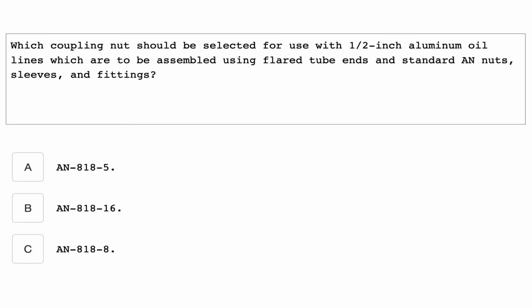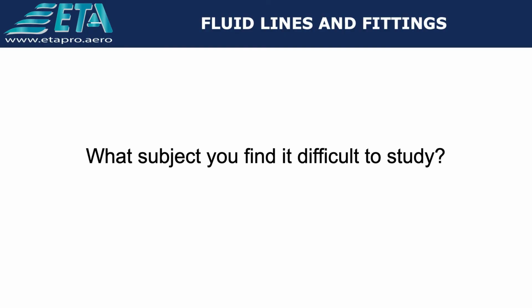Which coupling nut should be selected for use with half-inch aluminum oil lines, which are to be assembled using flare tube ends and standard AN nuts, sleeves, and fittings? AN-818-8.